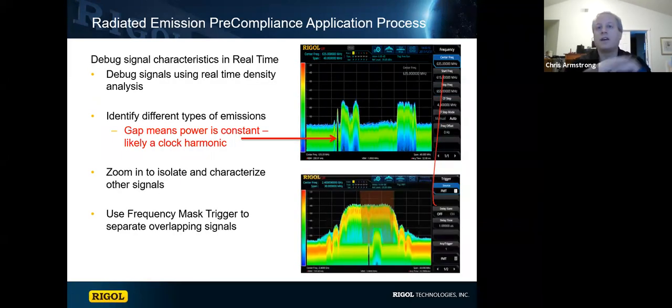And then I can often go into real time and capture them there and look at different ways to isolate those signals by seeing how they're modulating, right? So signals like this are more constant, because they never appear, or very rarely appear, down in the lower ranges. Some of these signals we can see are turning on and off part-time, so you can see how they're modulating. You can often use the waterfall chart as well. But with these clock harmonics, you've got different signal types you can debug with a real-time process like this.